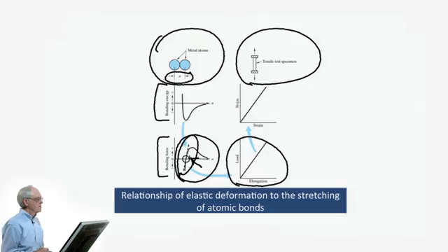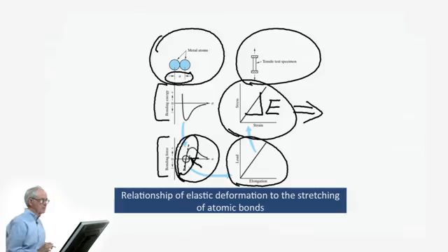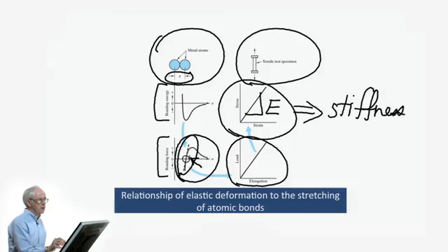that local atomic structure that we introduced in that very early lesson. And then when we normalize that data, the load versus elongation, by sample geometry, then we get the general behavior of the material of stress versus strain. And so then we get this general parameter of the elastic modulus, which again, in terms of just practical mechanical performance of the material, relates to the stiffness of that component in the overall engineering design.